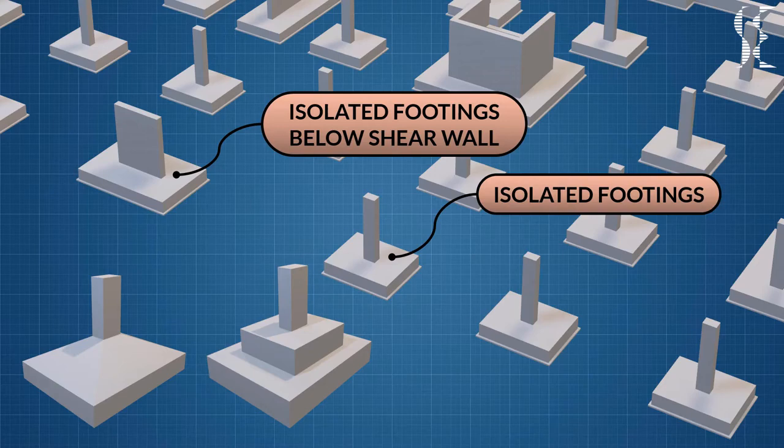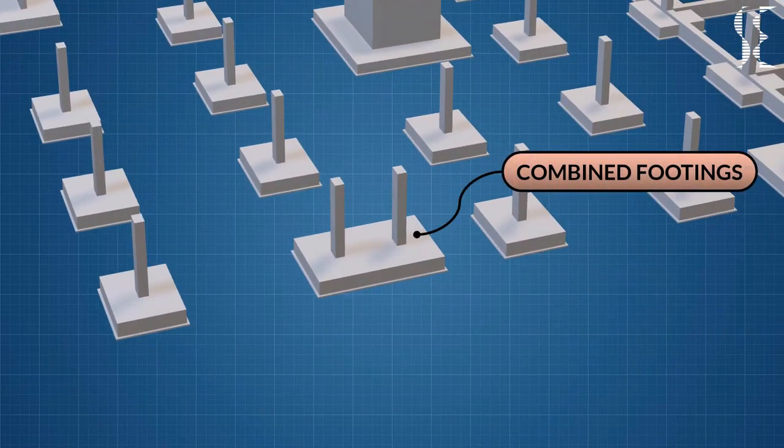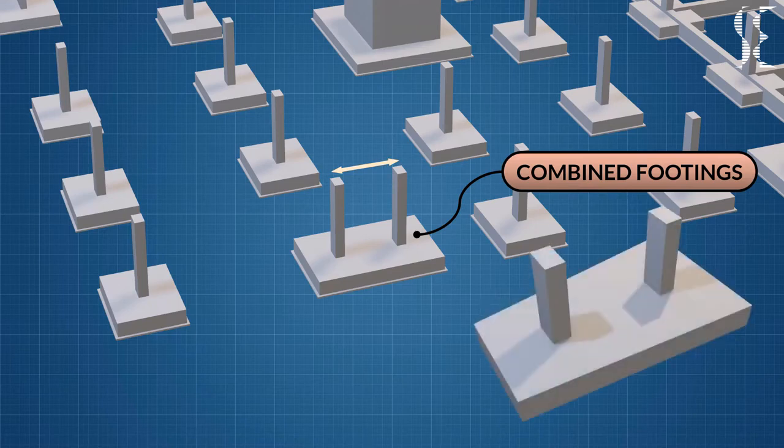Next come combined footings, which accommodate more than one column. When the spacing of adjacent columns is so close that separate isolated footings are not possible due to overlapping areas of foundations or inadequate clear space between two areas of the footings, combined footings are provided. Such footings are either rectangular or trapezoidal in plan, with or without a beam joining the two columns.